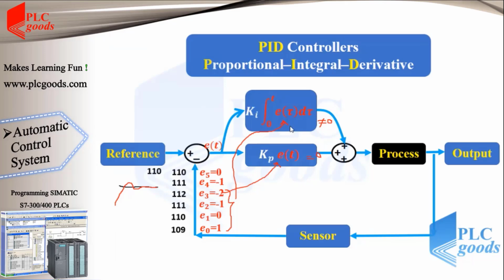Also, pay attention that although the integrator part of the PI controller is able to reduce the weakness of the P controller, which was investigated, it introduces a new problem to the performance of the PI controller, and that is the presence of fluctuation at the beginning of the red curve, and as a result it takes more time for the water level to reach the desired level.